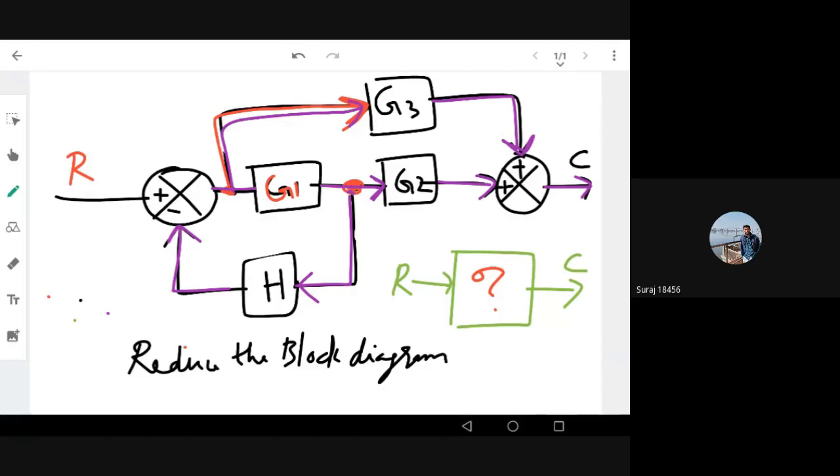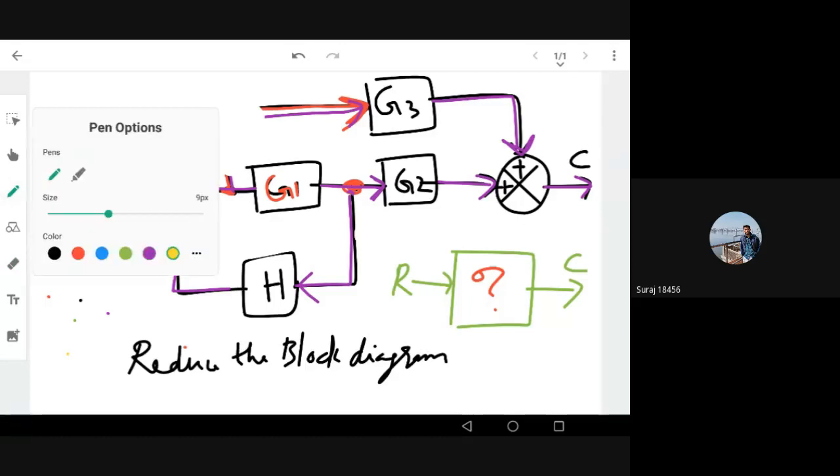Okay, so here I got some answers, but here you should remember that we cannot do any reduction here unless we change the branching point or node point, right? Because we know the closed loop is possible if this branch was not there. For example, if this branching was not there, then we could have easily made the feedback transfer function here.